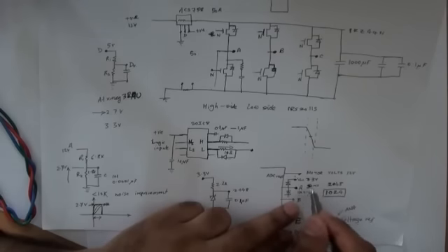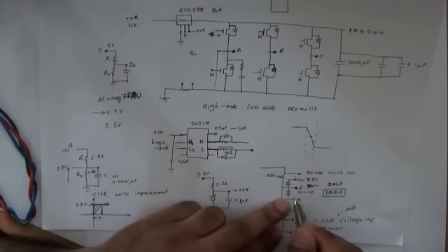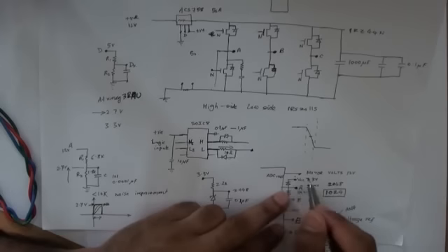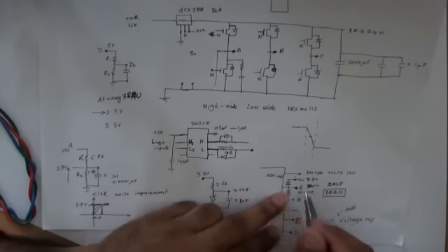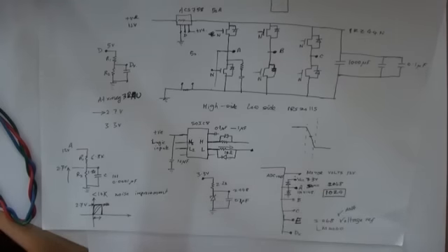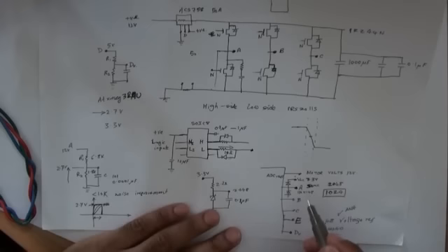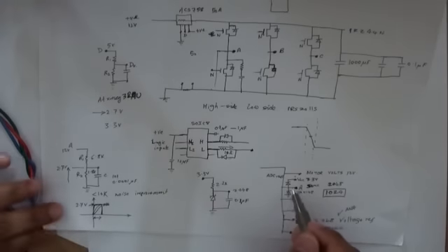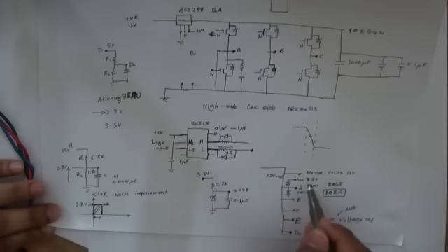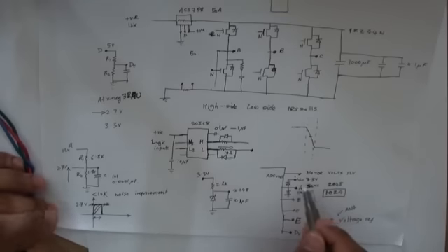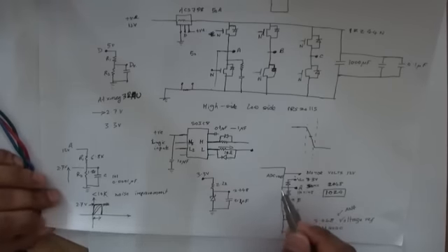So what that means is you could go below ground level by 500 millivolt, and you could go above 3.3 volts by 500 millivolt. I'm afraid that's as best as you can do with such a simple protection, and I don't think such a level will kill the ADC input for the microcontroller.